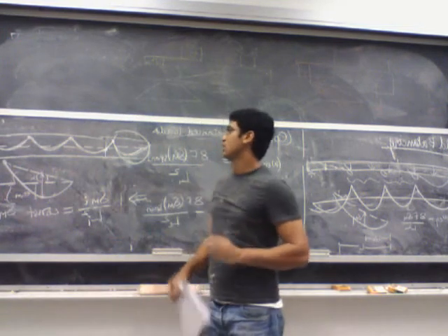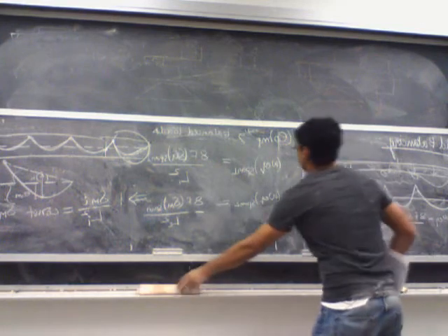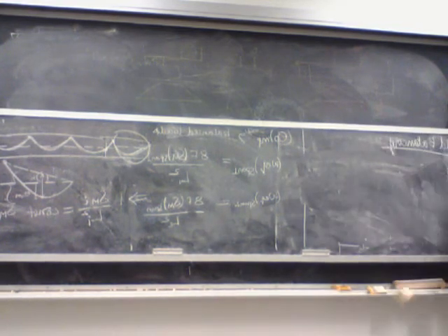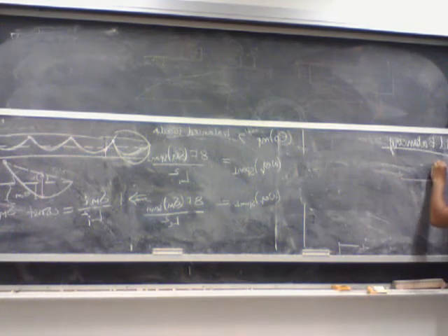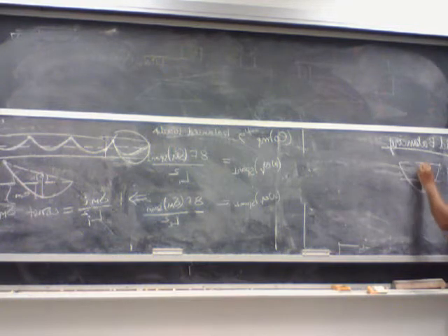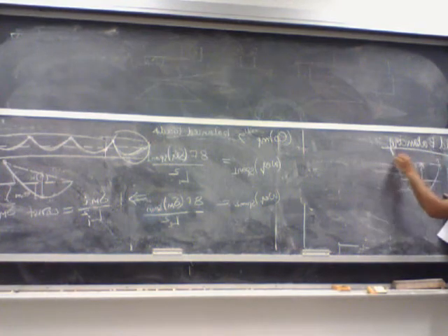Right? Now I look at this span. For the second span, my tendon profile looks something like this. In this case, my delta M is measured from the line connecting the two ends of the parabola. So this is my E naught m2, and this is 6 inches, 6 inches.